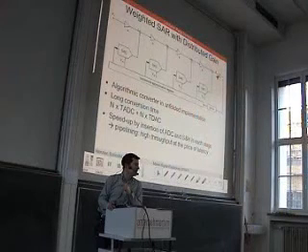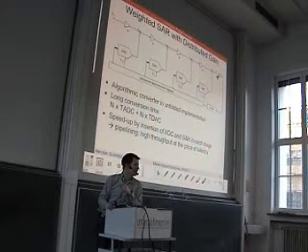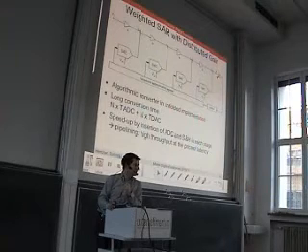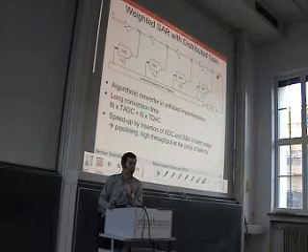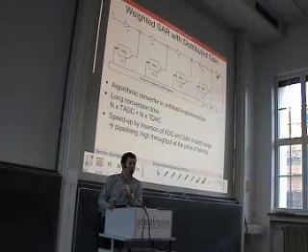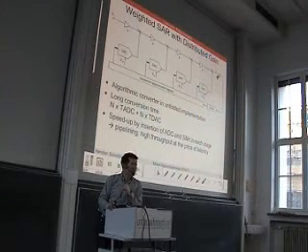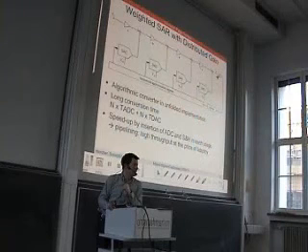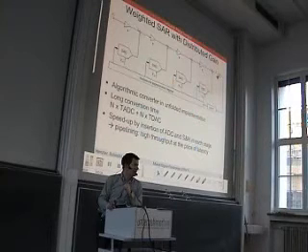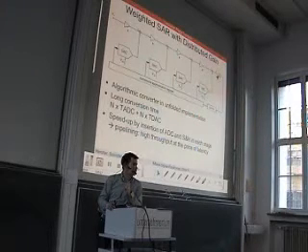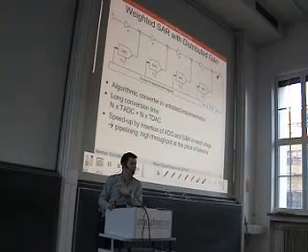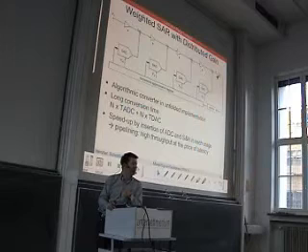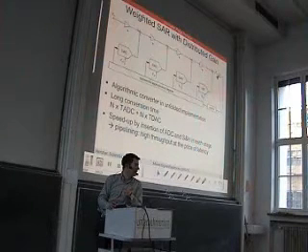What is done in digital design if the throughput through a signal processing circuit has to be accelerated? Did you hear anything about pipelining? Well, I guess in the digital domain you are aware what pipelining is, and now we should try how we could do a pipelining for this algorithm.